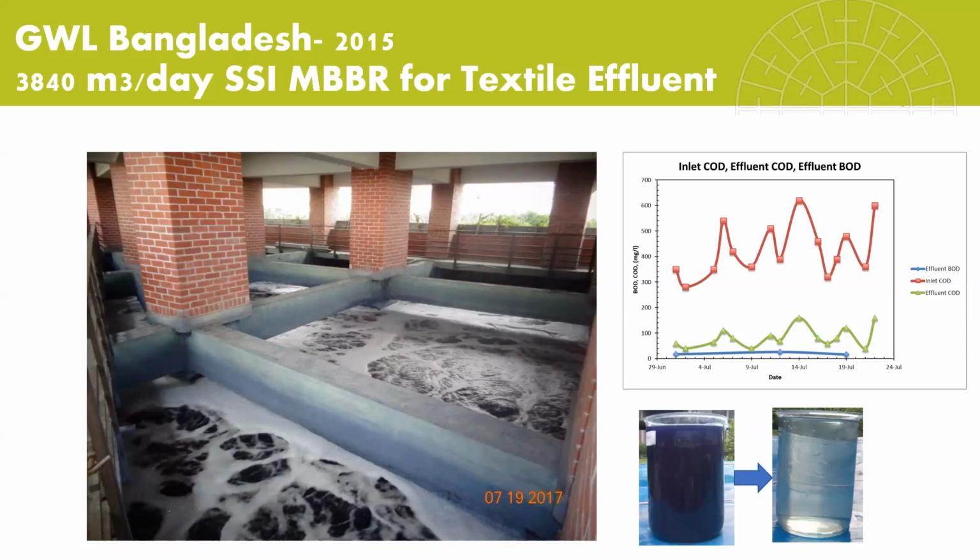It's not that biological treatment can't work above 37. It's just there is a range between about 37 and 42 degrees Celsius where any biological system is going to have issues, because it's basically a boundary between different types of bacteria that can survive. So with systems hovering between that 37 and 42 degree mark, it can create a lot of issues with biological treatment. So if we can keep it above 42 or below 37, we're generally going to be in much better shape.